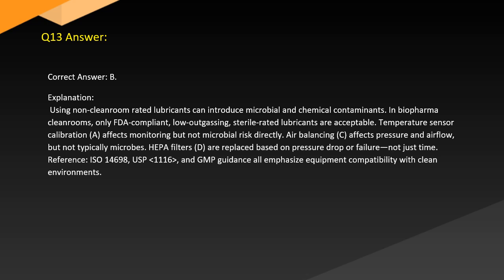Correct answer: B. Explanation. Using non-cleanroom rated lubricants can introduce microbial and chemical contaminants in biopharma cleanrooms. Only FDA-compliant, low-outgassing, sterile-rated lubricants are acceptable. Temperature sensor calibration (A) affects monitoring but not microbial risk directly. Air balancing (C) affects pressure and airflow but not typically microbes. HEPA filters (D) are replaced based on pressure drop or failure, not just time. Reference ISO 14698 and USP and EMP guidance, which emphasize equipment compatibility with clean environments.